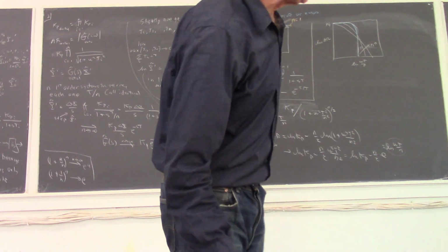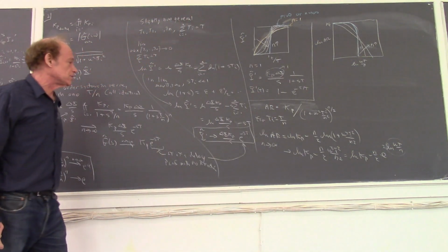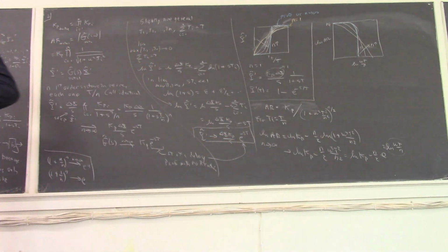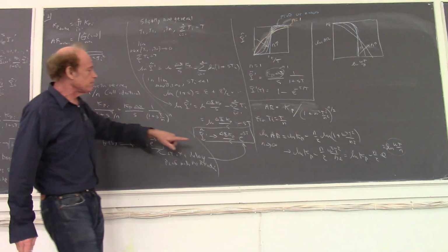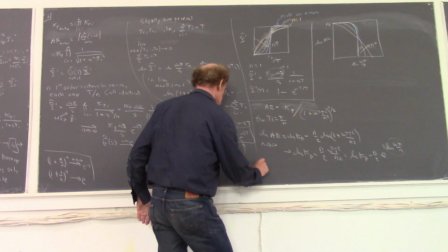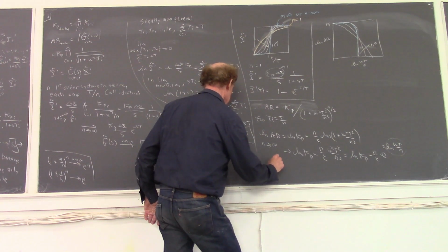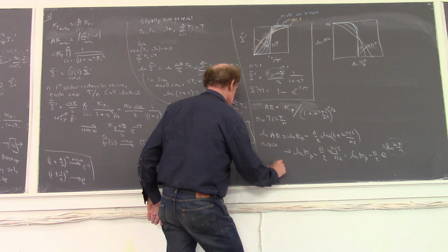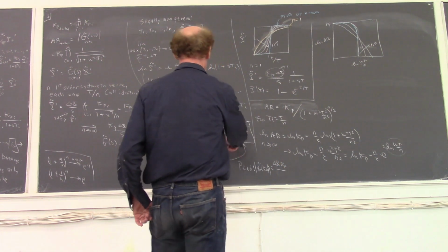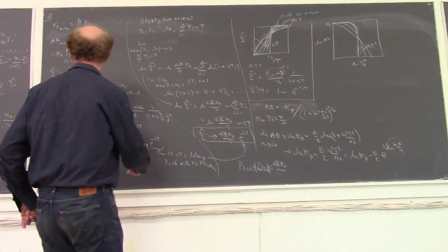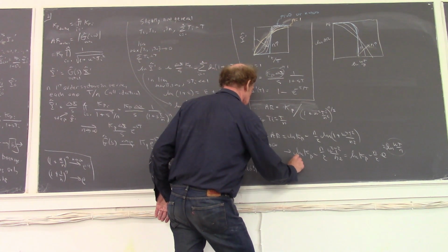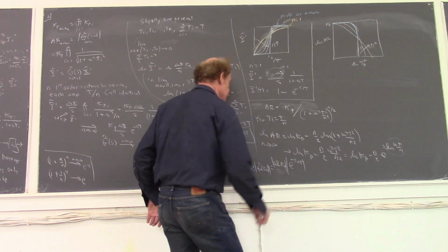And I want you to notice that if I were dealing with the plug flow reactor, remember the amplitude ratio is the magnitude of G tilde of i omega. For the plug, G tilde of i omega, so I don't need the delta x, just Kp. So for the plug flow reactor, I have e to the minus i omega t. And I have to take the magnitude.